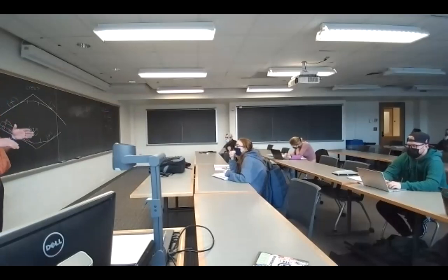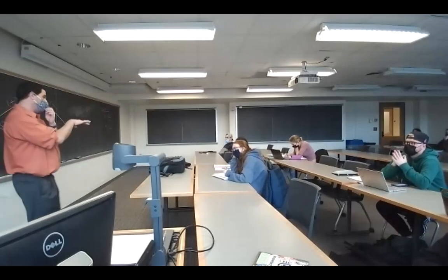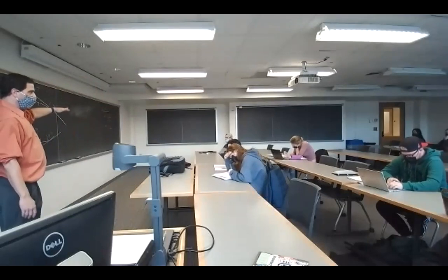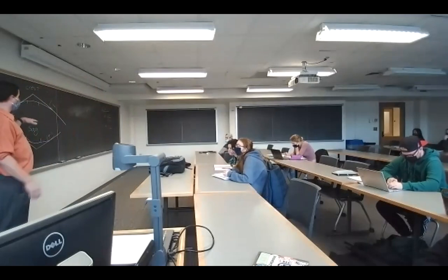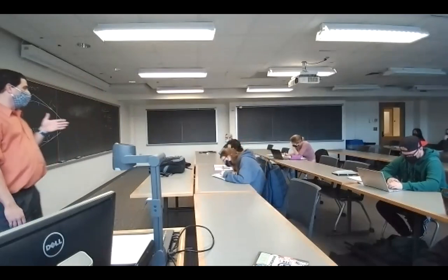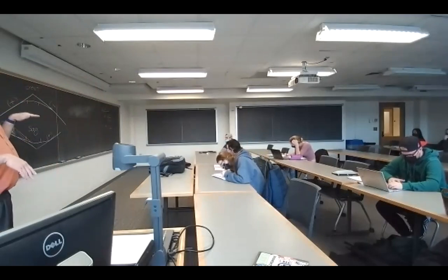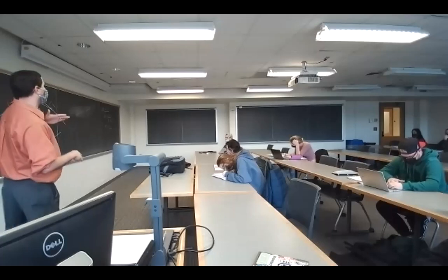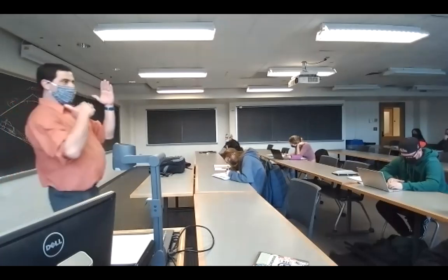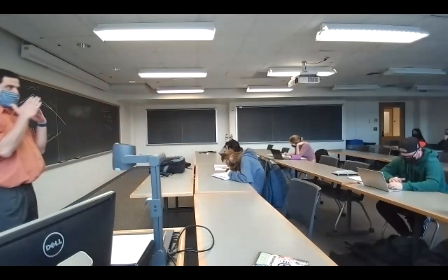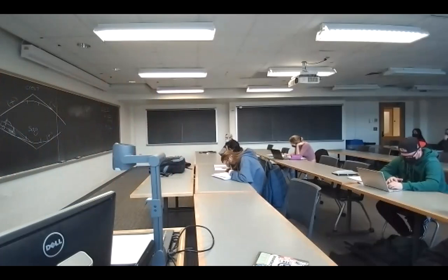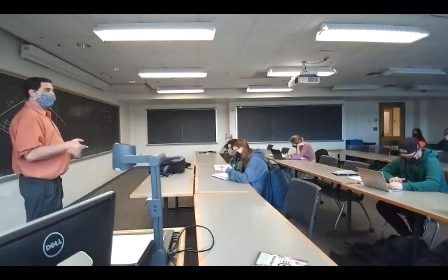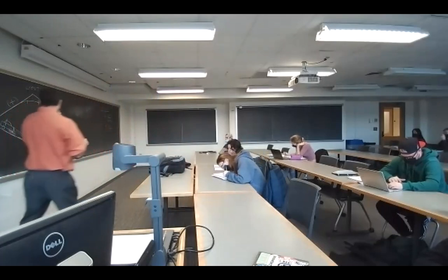But when you do your profile, we're going to exaggerate the horizontal and vertical scales so you can see the changes in grade. I'll talk a little bit about that. Your horizontal scale is going to be, say, 1 inch equals 50 feet. But your vertical scale isn't going to be 1 inch equals 50 feet. You exaggerate that so you can see the curve more clearly. Because if you looked at the plan and you saw the curve the way it's going to be in real life, it's going to look so gradual that you're not going to be able to pick up the detail. So in roadway design, there's always a difference between your horizontal scale and your vertical scale. And it's usually a 10 times exaggeration. So if your horizontal scale is 1 inch equals 50 feet, your vertical scale is 1 inch equals 5. If it's 20, it's 20 and 2, horizontal and vertical. 1 to 10, you get the idea. Right? Okay.